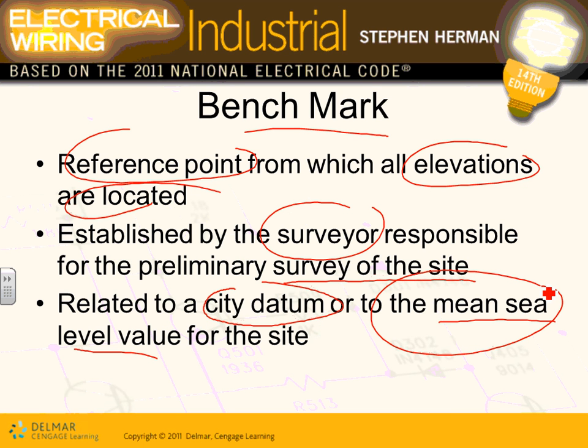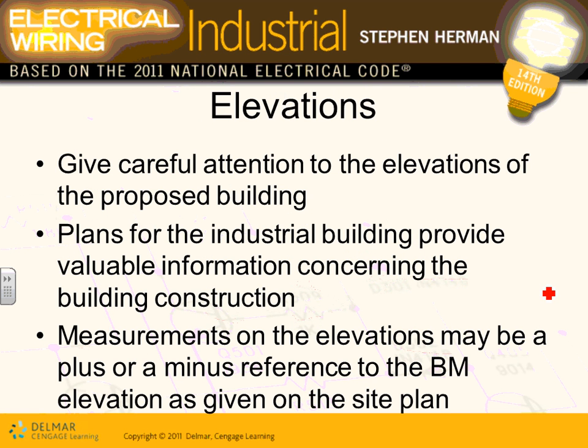We have a benchmark. That benchmark is 750 above the sea level, and from that benchmark we measure everything else. Here's my benchmark, guys, for this project. Derek, I just put the blueprints right in here. My benchmark is 745.68 feet above the sea level. Elevation.